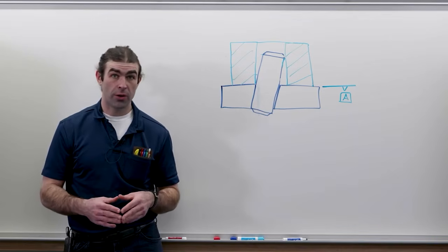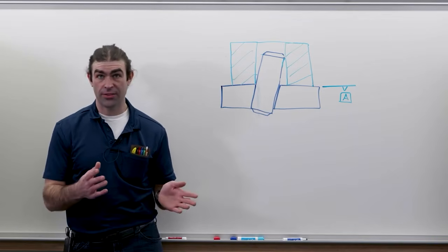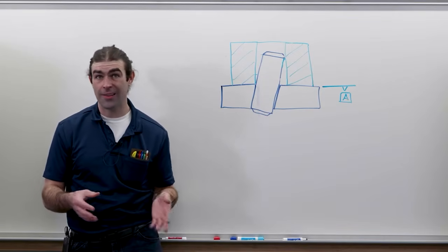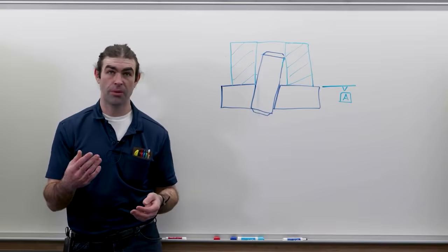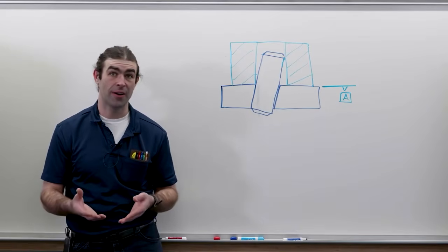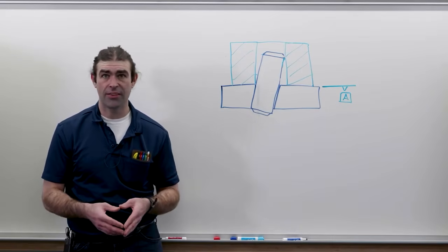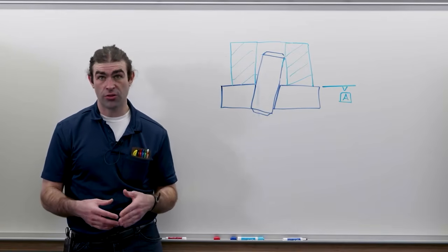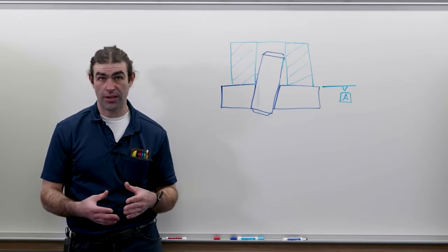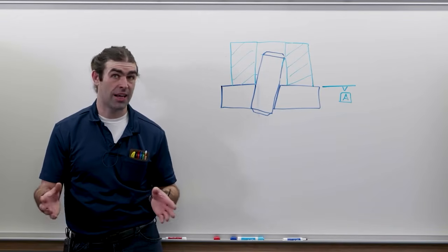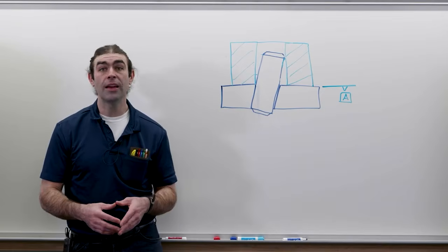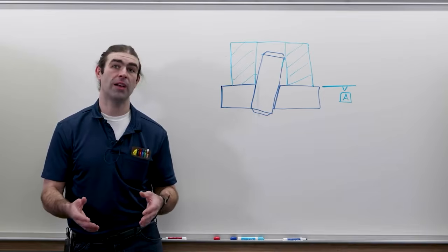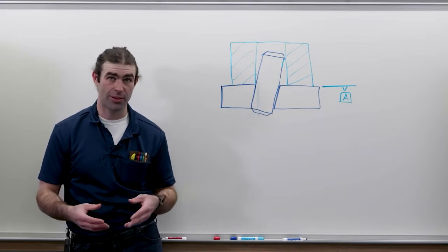Angularity is used for angles that are not 0 or 90 degrees, but confusingly, you could use angularity in the place of parallelism or perpendicularity. That's a newer thing in the ASME standard. The way you know the difference is just looking at the lines on the drawing. So if the lines are drawn as perpendicularity and then it's not stated anywhere that it's not 90 degrees, you assume it's 90 degrees. Same thing with lines that are drawn parallel. This is fundamental rule J from the ASME standard.